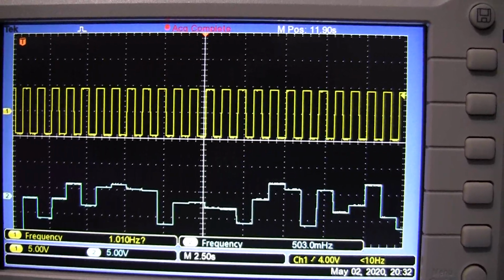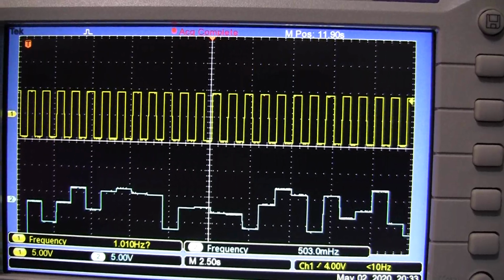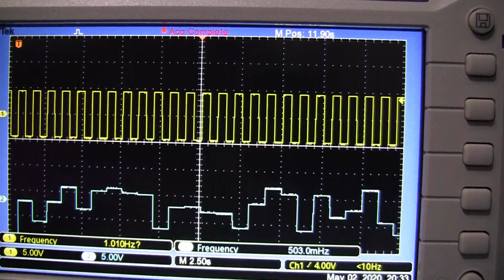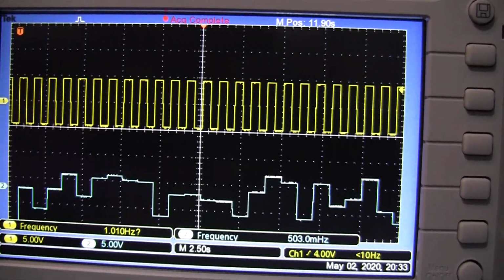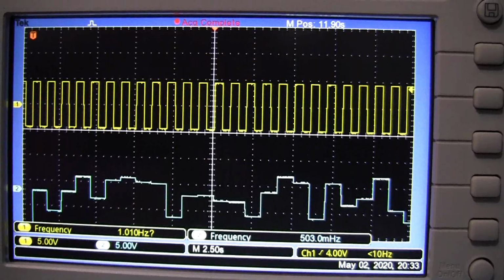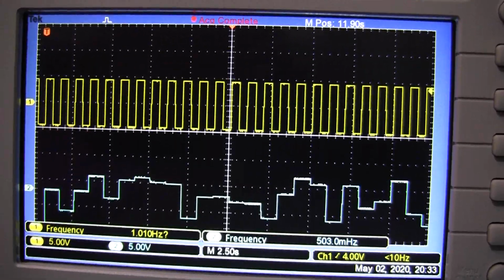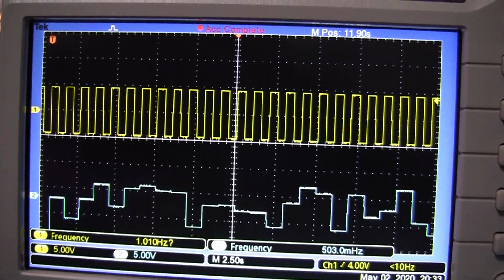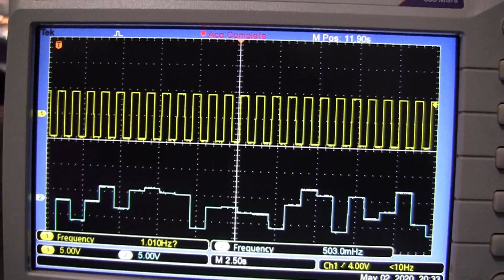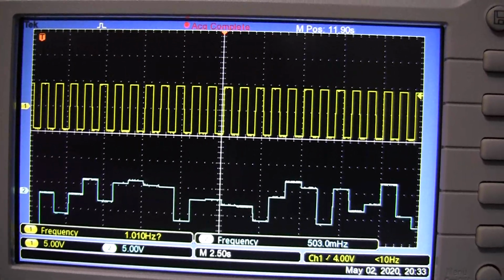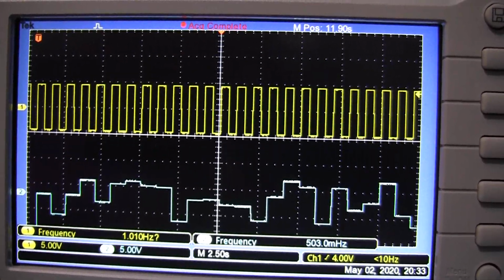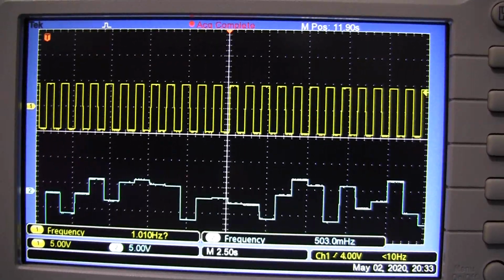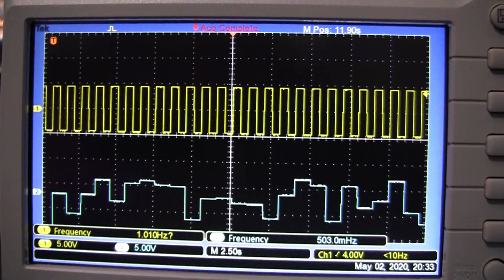But clearly you see that our control voltages are divided into either a cyclical thing, which is like what we're using with our envelope generator, a random thing like what we have here, or perhaps a single trigger that goes through a particular cycle. So if we have a single trigger, that would correlate to some kind of timbre change on a note. If we have a continuous cyclical thing or a random thing that continues over time, that can be used as a modulation.